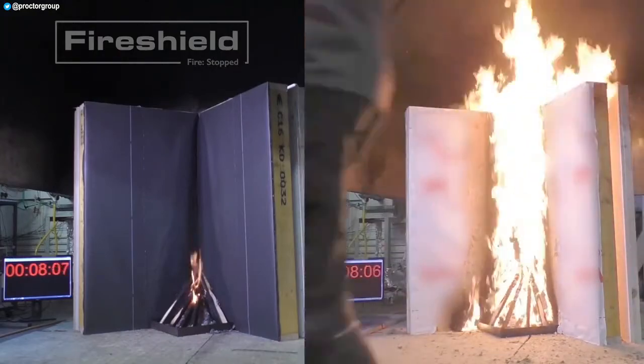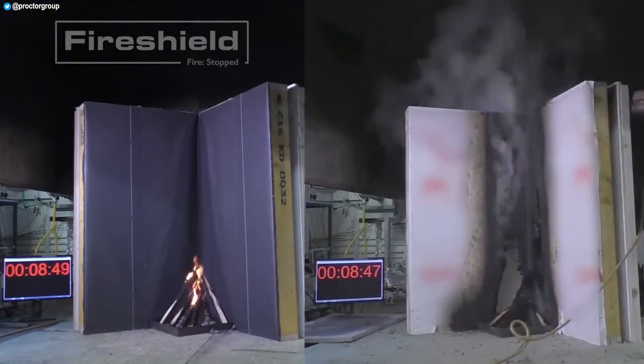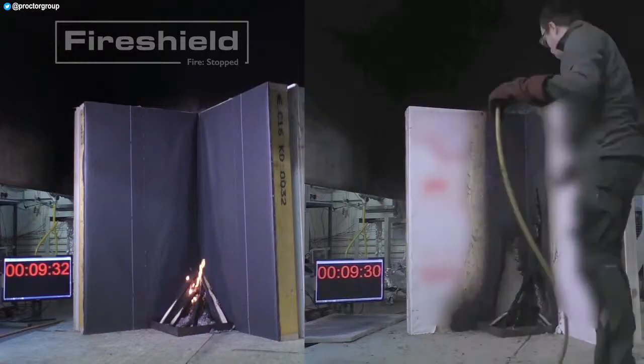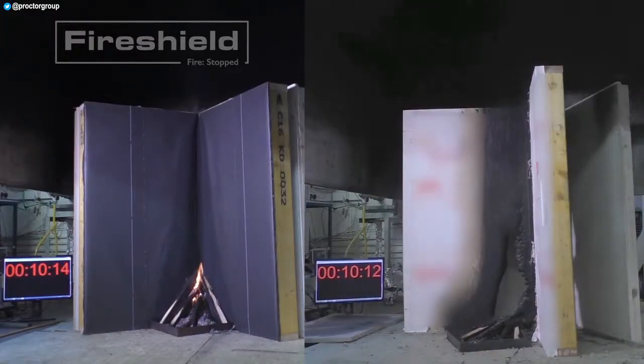The standard Class B membrane, although it shrinks away and does not contribute to the development of the fire, does nothing to protect the structure or delay the progression of the fire. Used in this way, Fire Shield can help prevent fire from outside the building causing damage, both during construction and in service. During the construction process, Fire Shield can also be used on the external cavity face to improve fire robustness of closed panel assemblies when installed over external sheathing alongside suitable non-combustible internal linings.